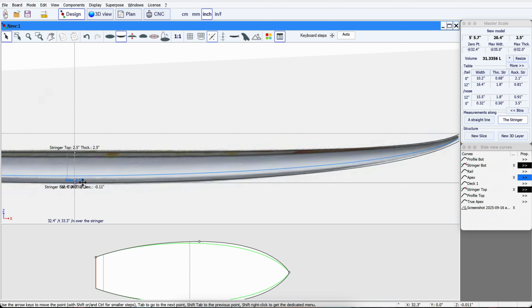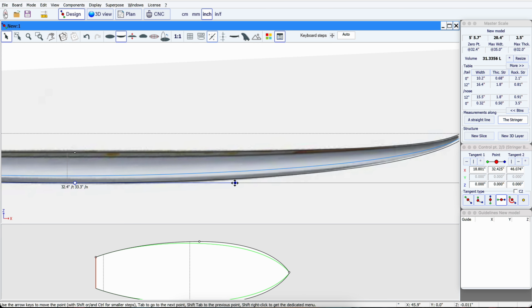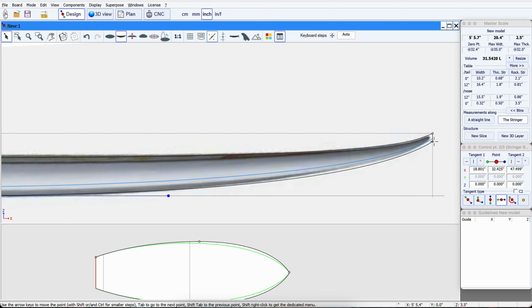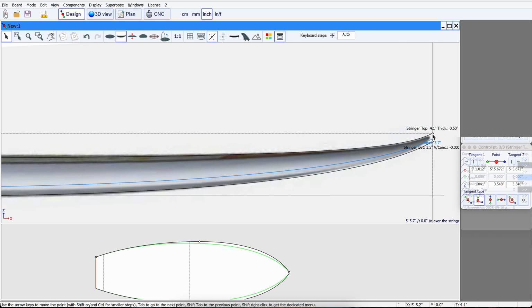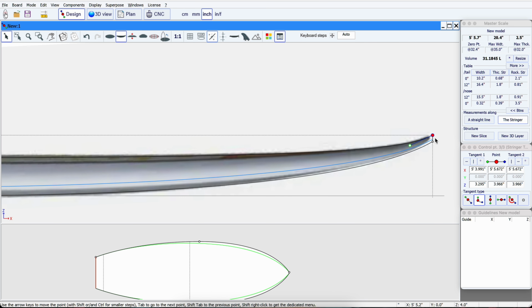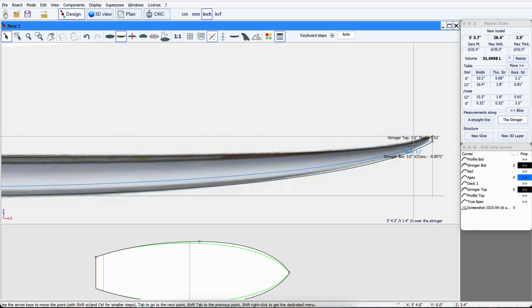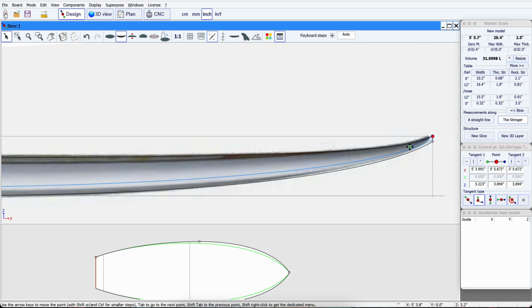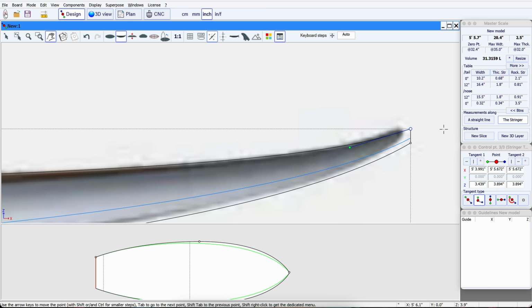And if you want to have a slightly easier entry, you can always extend this point slightly to do a slightly more stage rocker. So again, everywhere there's a bunch of small adjustments, and again back here I'm going to put this down to make the thickness. And this is actually an interesting part that I want to address. You see this flip on the nose that this board has. Keep in mind that basically the overall rocker is quite low and gradual, and then more or less from this point you have a kind of aggressive flip. Do not go crazy if you have this on the board and you're designing your rocker.